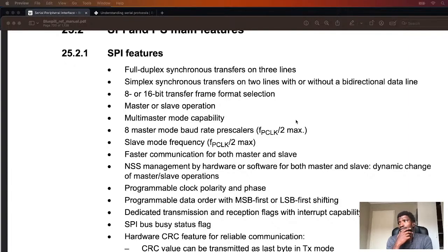And then you can set a baud rate, which is the prescaler for the clock. Data on SPI is limited to travel as fast as the clock pulses, so you can set how fast the clock pulses using the baud rate prescaler. A prescaler is basically a divider. You start with 100% of speed, and then there are dividers that let you have 100 divided by 2, divided by 4, and so on, all the way to, I think, 16 if I recall correctly.